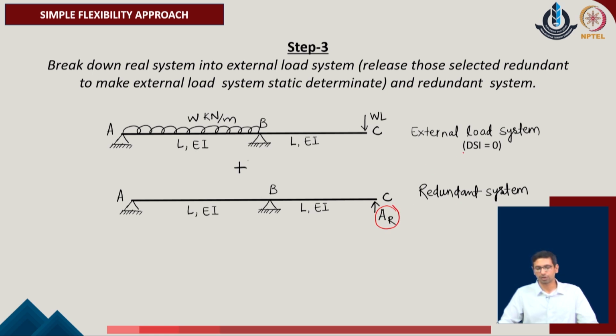An important thing to note is that for both of these systems which we have identified, the degree of static indeterminacy is 0, which means I can solve these two systems by the simplified procedures known to us. The only thing is Ar is an unknown parameter. So, now we will evaluate the response of the system, or the displacements, and fit the condition of compatibility to find the value of this unknown parameter Ar.